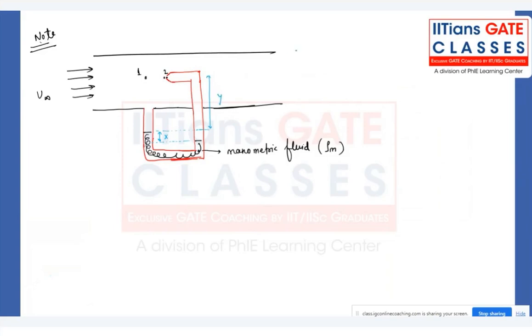So point number one is just outside the tube. We can have an imaginary extension, like this. There is no tube actually extended up to point one; it is just an imaginary view, right? Now when the flow is happening like this, and your fluid is going like this, that is my static pressure, right? You know how the working principle of a manometer works. So we have to measure the pressure till here.